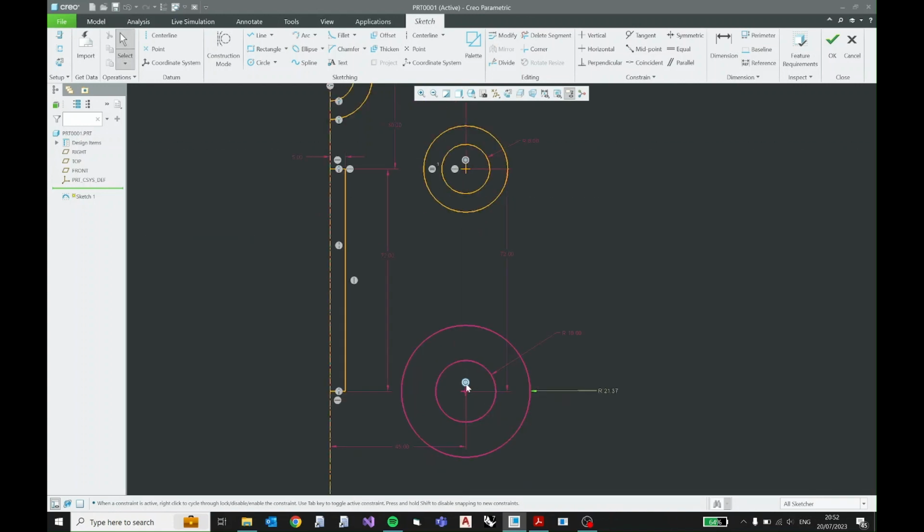You can also see that this constraint is activated, which is a coincident vertices, or you can also consider it as concentric circles, which means that the center of the circle lies with the center of the circle. So we cannot, oops, sorry, I forgot to lock it. 20.0. So now you can see why we need to lock this, because we can change them intentionally or accidentally as well. So now we cannot change any aspect of this circle because it's fully constrained now.